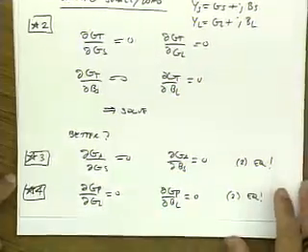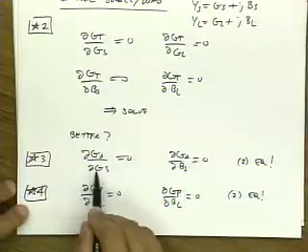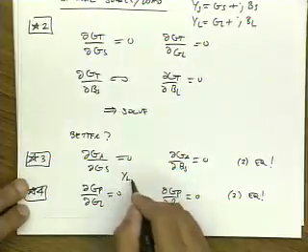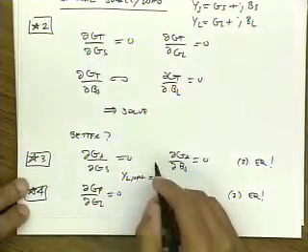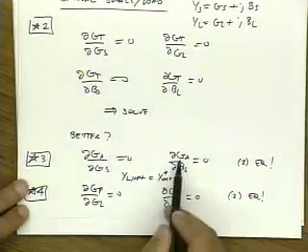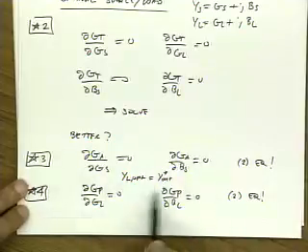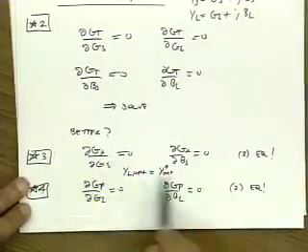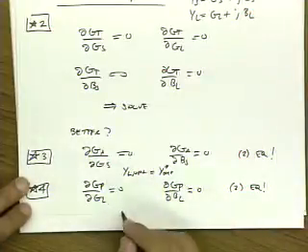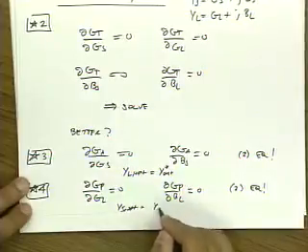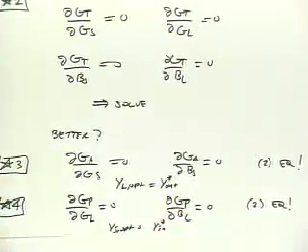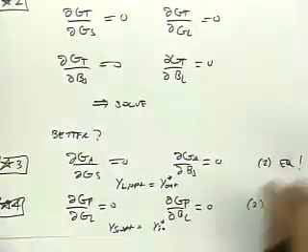And when you're done, so for instance, if I solve for GS opt and BS opt from these two equations, I can find YL opt by simply making YL equal to Y out star. And Y out, remember, is a function of YS. And so this is a recipe for finding the optimal load. So even though this only gives us the optimum source, with one line of algebra we can find the optimum load as well. And here, YS opt we can find by doing the same thing. Okay? Any questions about that? Does that make sense? Good.